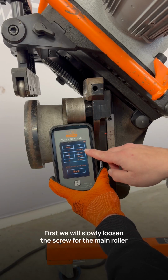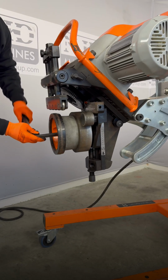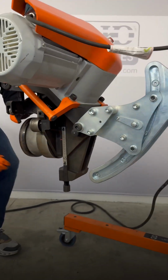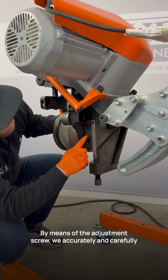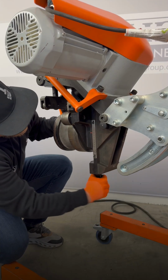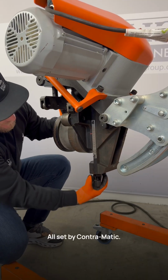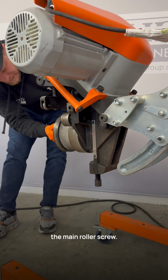First, we will slowly loosen the screw for the main roller to allow precise adjustment. By means of the adjustment screw, we accurately and carefully set the value for the initial cut, namely 15 millimeters. All set. We will once again carefully and precisely tighten the main roller screw.